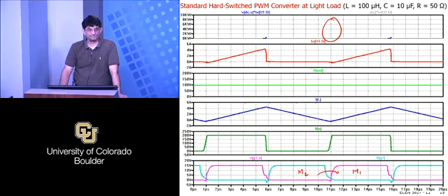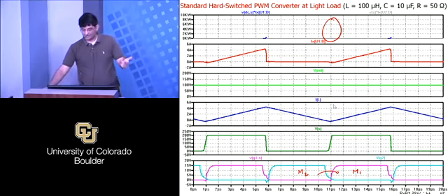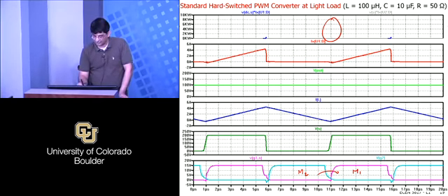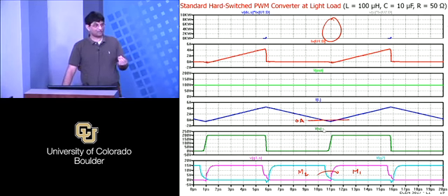In the first DCM. Yeah, basically the average current has gone down, ripple has stayed the same. So at that transition, which was troublesome, even the hard switching converter now has negative current, right? So no new phenomena, it's the same old phenomena. It just happens that at this operating point, with the inductor size, the ripple was large enough to give you zero voltage transition even on the M2 to M1 transition.